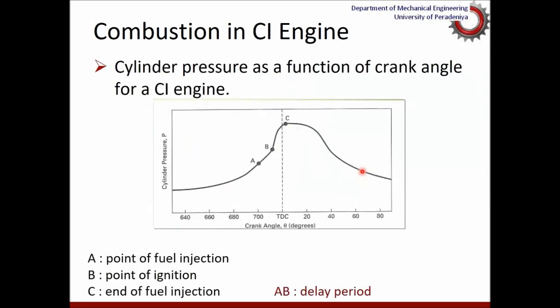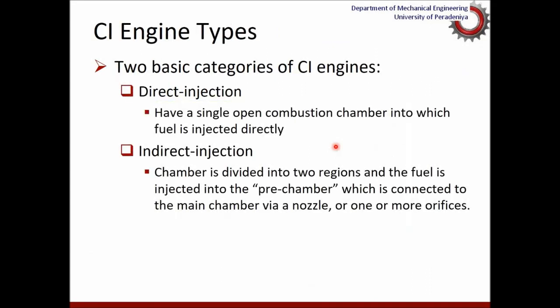So this is the pressure diagram, where this is the point of injection, B is the point of ignition, and this is the end of injection. So the pressure rise is somewhat different from the pressure rise in spark ignition engines.